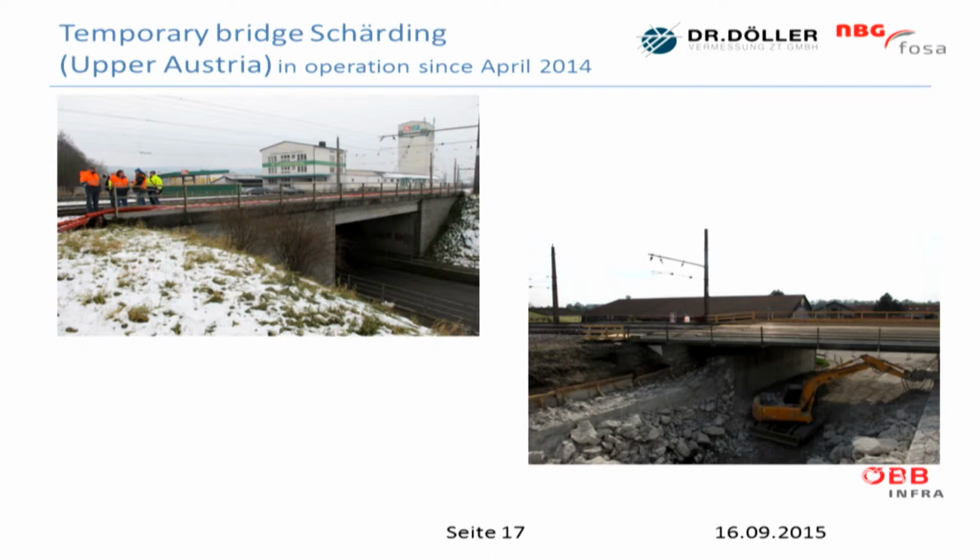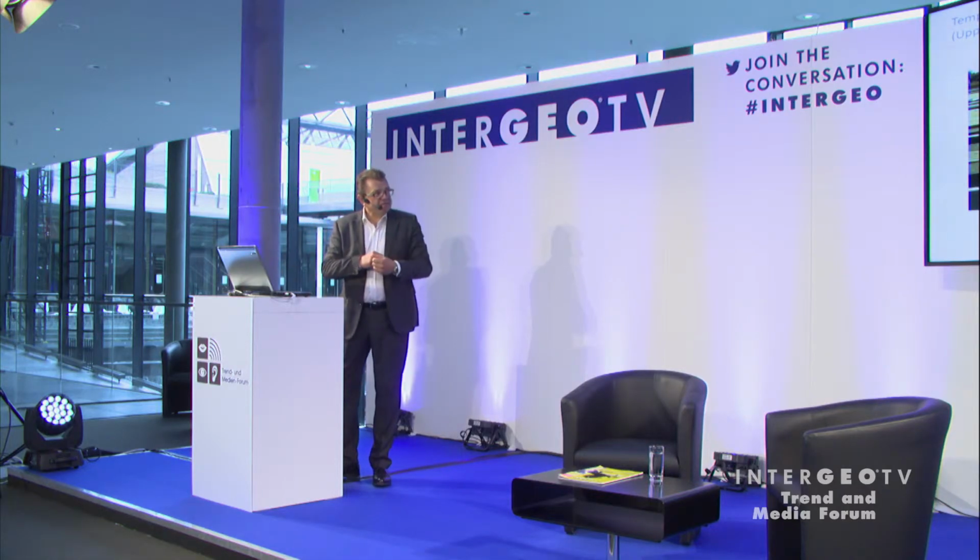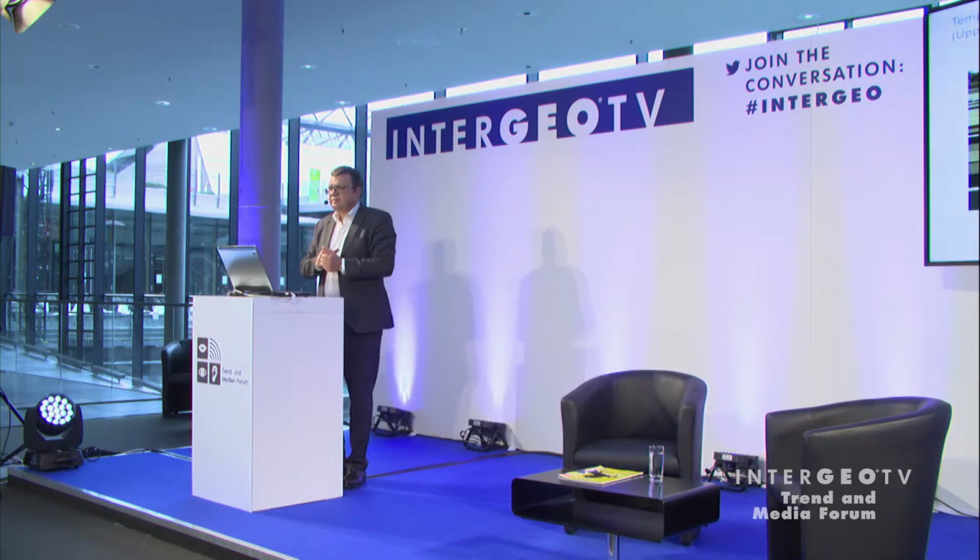And we installed our bend line system there about 6 months ago. Bend lines, just to explain, is a line of 5 meters with FBG sensors up and down, and through the horizontal movement, we calculate the vertical extension of the temporary bridge, and also there we installed an alarm system 24 hours a day for our partners of ÖBB.